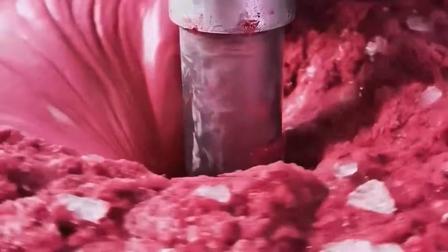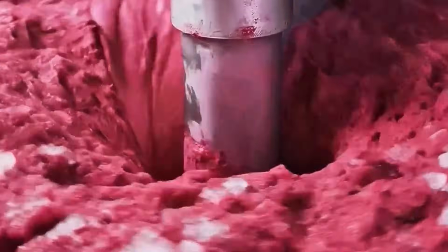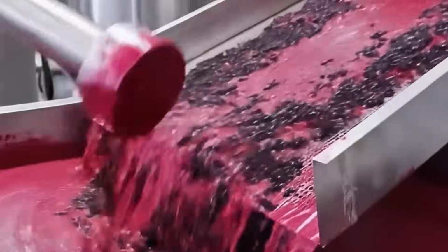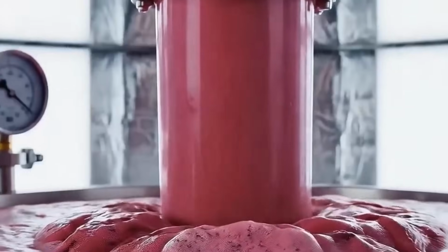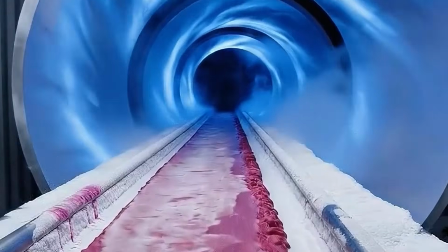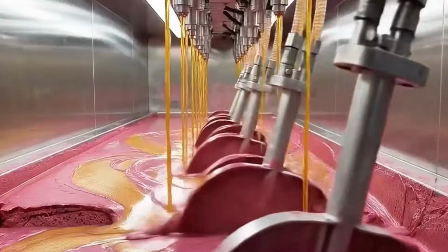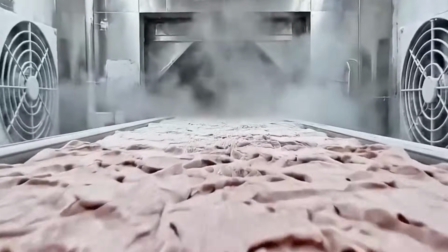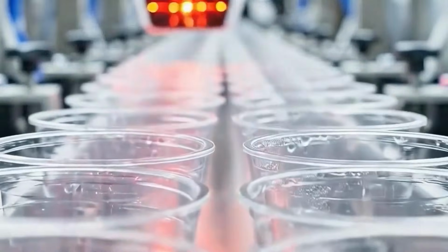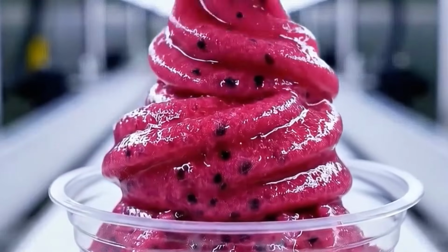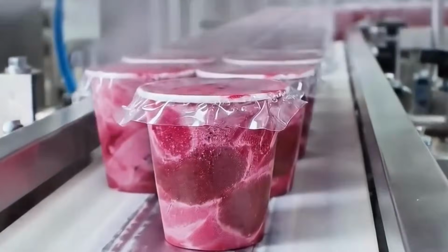Citric acid and malic acid are most commonly used, added via microdosing pumps based on real-time pH feedback from inline probes. The typical pH target range for sorbet mix is between 3.4 and 4.2, depending on fruit type and desired tartness. Some blends may also include buffering salts or fruit-derived aromatic extracts, introduced in sub-gram quantities with gear-driven precision pumps.